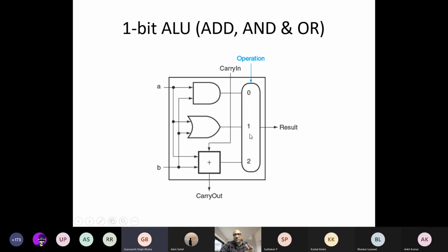With 2 bits, you have 4 possibilities, so up to 4 outputs can be controlled with 2 inputs. If you have only 2 inputs, to select one among these 2, a single line with 1 control bit is sufficient to select either 0 or 1. But since there are 3, you need 2 control bits, and with that you can select one among these.